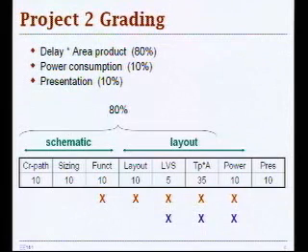Then you have to do critical path analysis. That's going to give you some points. Then you have to do sizing of your critical path. And finally, you have to do a functionality check in schematic. Early on, you have to check functionality to make sure that your design works. If it doesn't work, all the other results that come after that are suspicious, and everything falls into water.